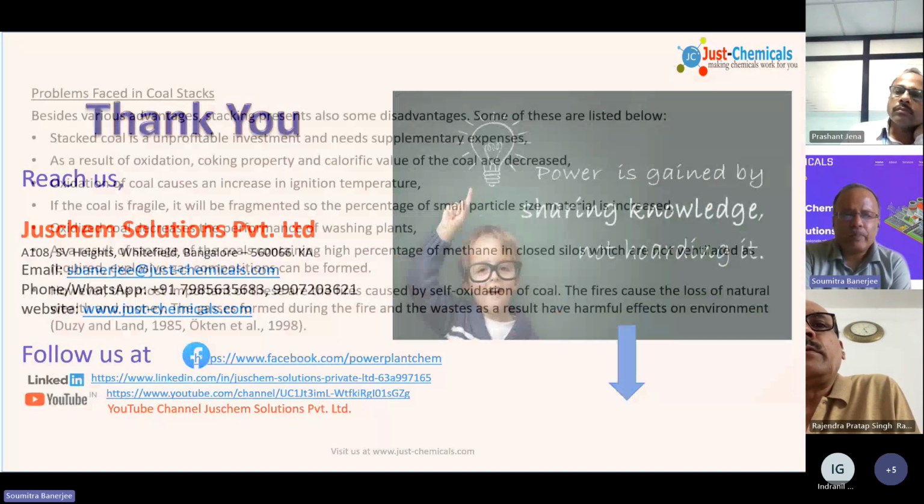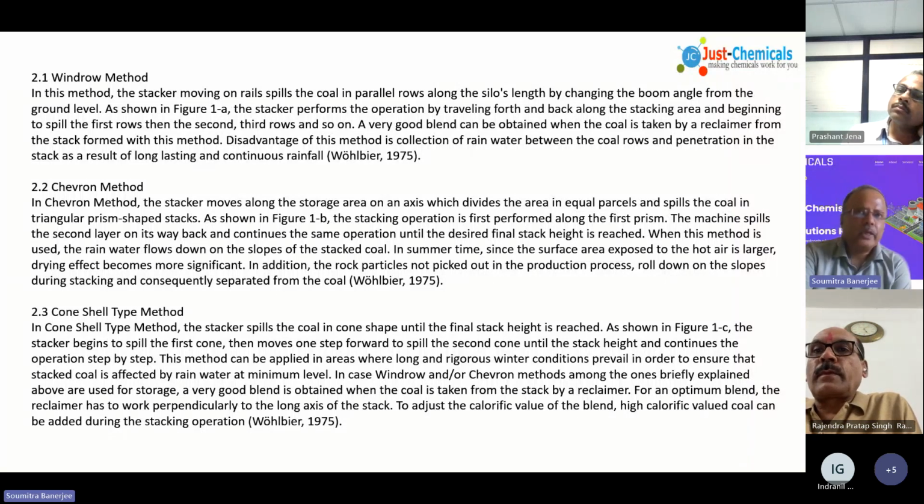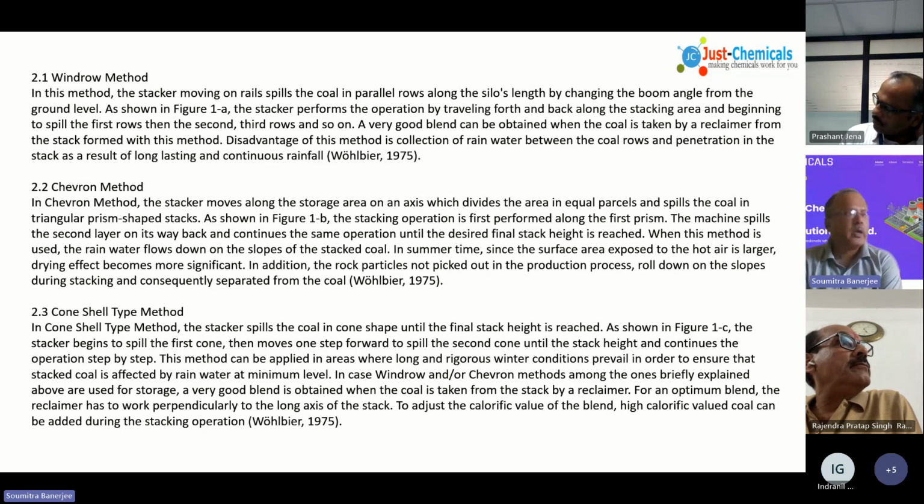But we also face some problems regarding GCV balancing. Whatever GCV we are getting as input, say the number of trucks, or the kg received into the kilocalories, converted into gigacalories, after 1 month you do a GCV balancing, meaning what you had, what you got, minus what you burnt. And when you do the physical verification, you will find a difference of 500 to 600 kilocalories.